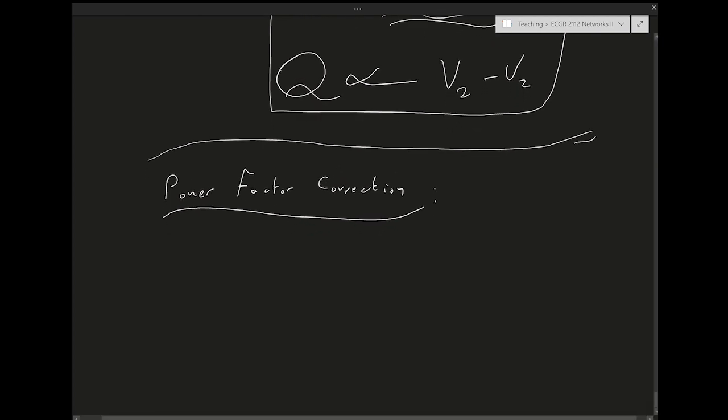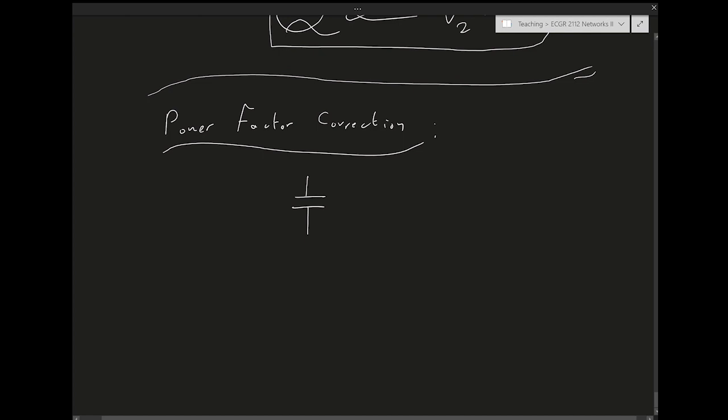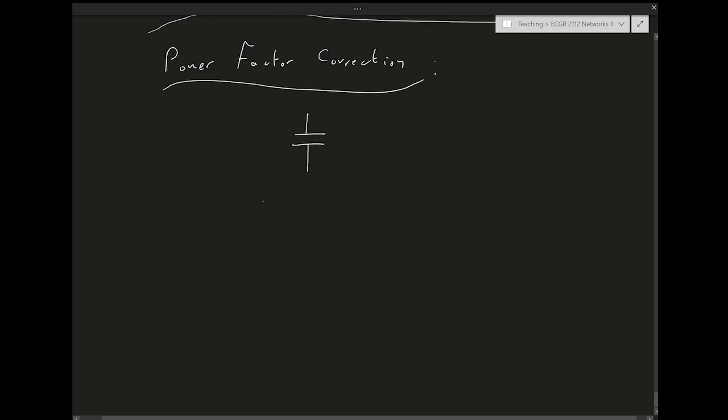First, to do power factor correction in 3-phase circuits, it's the same deal. You have to add capacitors in parallel to achieve the power factor correction. The only thing is, in this case, it's not a single capacitor you're going to add. It's going to be a 3-phase capacitor, either a delta connected 3-phase capacitor, so you'll have 3 capacitors actually, or a Y connected set of capacitors like this. But it will be capacitors that are going to do the trick.